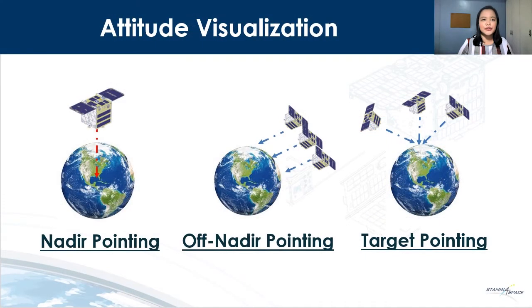Next is a visualization of satellite attitude. In the case of Diwata satellites, 3 attitude control modes are typically used, namely nadir, off-nadir, and inertial pointing modes. An application of this feature would be in the verification of external noise in an observation procedure that was not performed correctly. By using MATA Quick Simulate mode, a future observation could be planned to avoid similar mistakes. This feature can also be used for testing other attitude control systems, like PID controllers and reinforcement learning algorithms.